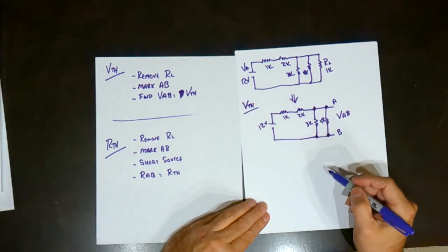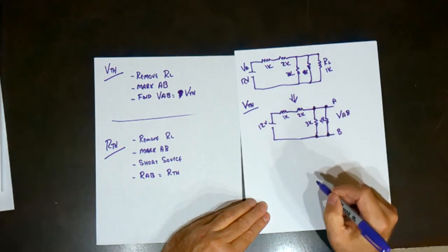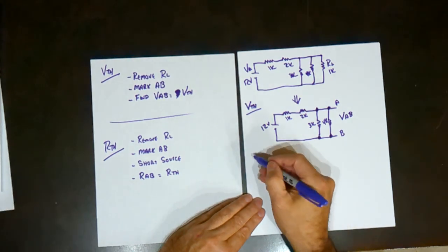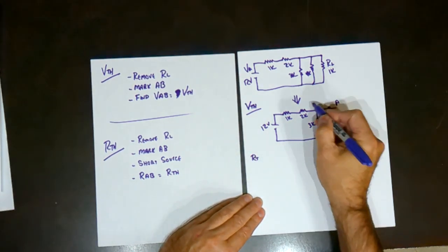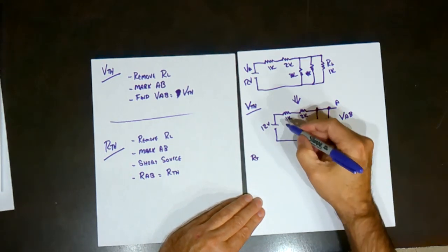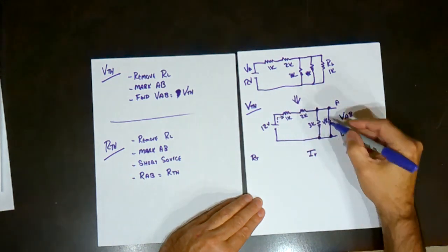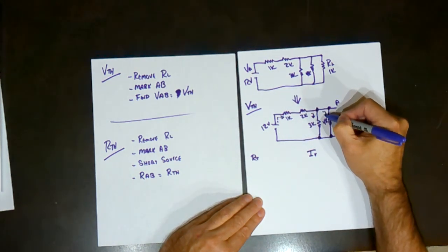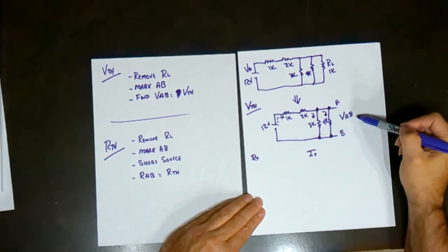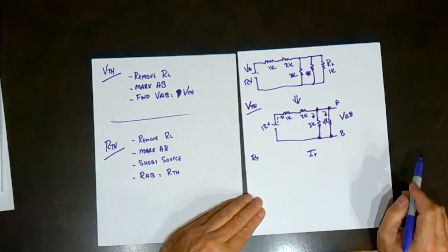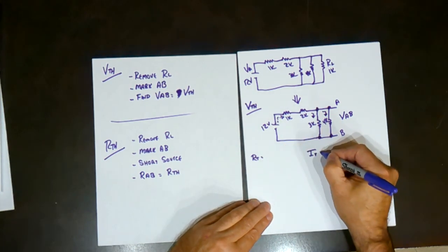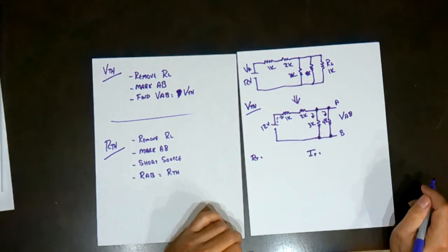So if we were given that circuit and all we had to do was calculate the voltage across that 4K resistor, should be not a problem. So first thing we want to do is find our R total of this circuit, so that we can calculate I total, and then we can see where the current is going. And if we can figure out this current down this branch, we can find out what that voltage is. So there's many ways to solve this. I'm just going to follow the simple current way.